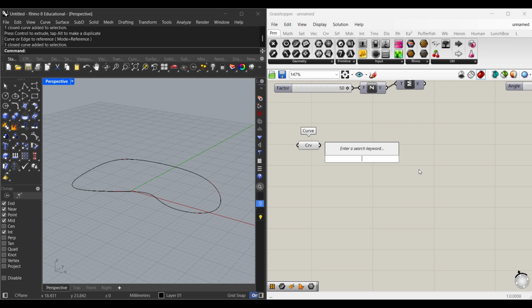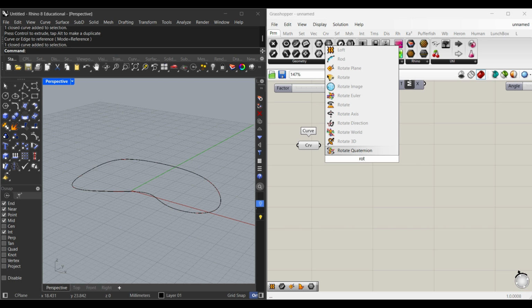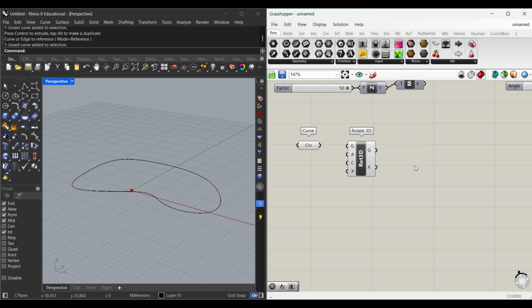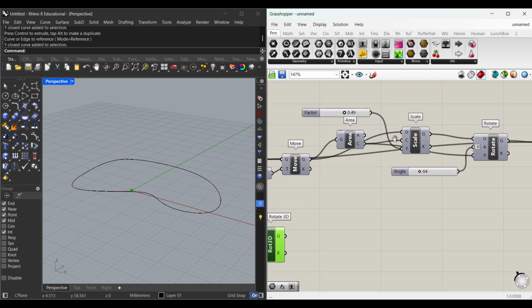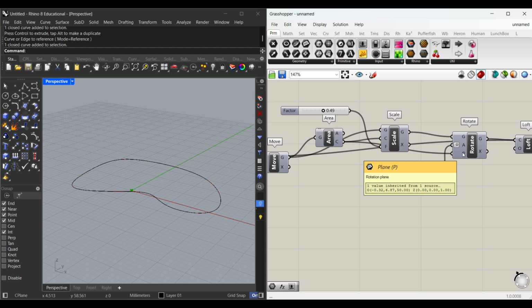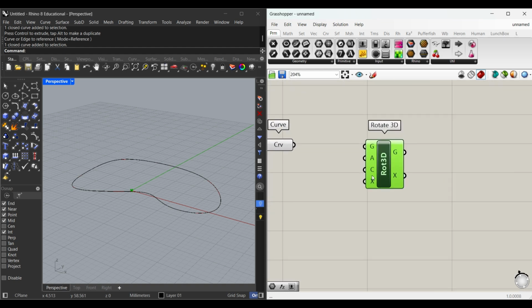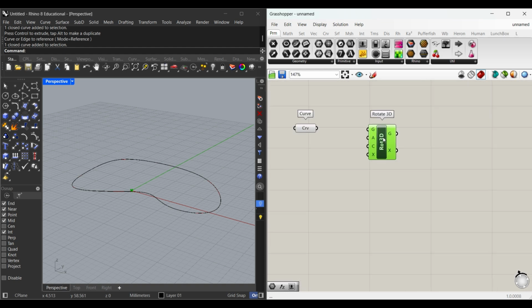the Rhino space. So if you want to rotate it in Grasshopper itself, other than the XY plane, we should rotate it in 3D. So what I want to do is sort of rotate it this way, up on itself. And so yeah, the rotate 3D command wants geometry, an angle, the center point similar to what we had here for our plane, and an axis similar to move.